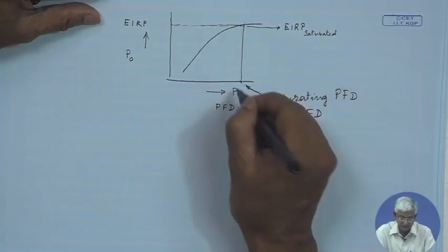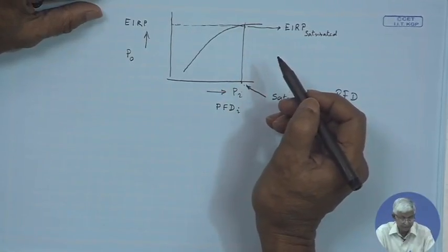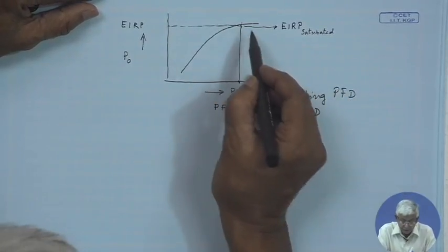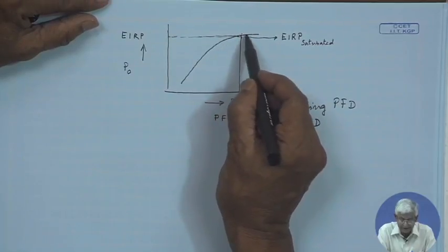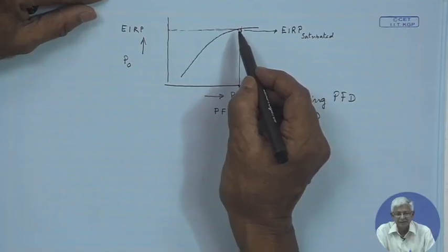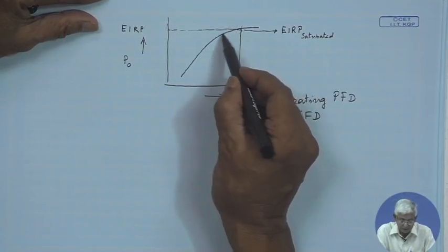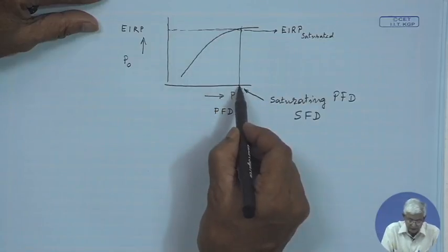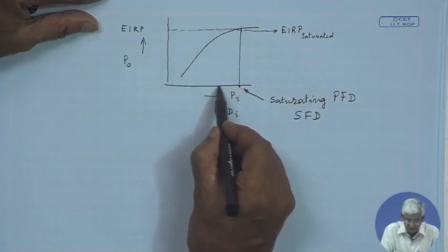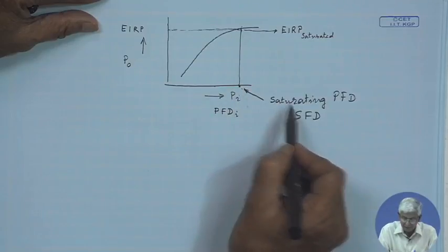These two values are specified, that is the input point and the output point. Now, we do not like to operate in the nonlinear region. We have seen that simple nonlinearity generates lots of spurious signals. Therefore, we must operate in the linear region. So, the input maximum has to be reduced, that is, backed off from SFD.